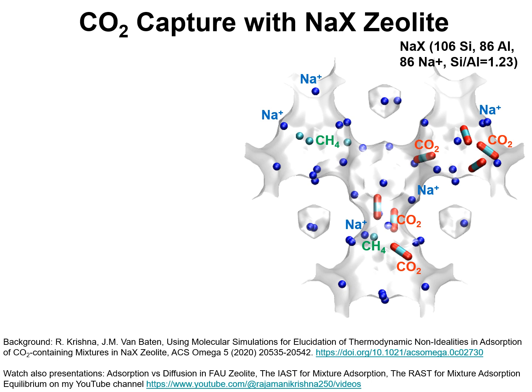PSA technologies. For post-combustion CO2 capture, 13X zeolite is considered to be the benchmark adsorbent with the ability to meet the US Department of Energy targets for CO2 purity and recovery. The commercially available 13X zeolite is a sodium cation exchange faujasite zeolite with silicon to aluminum ratio of about 1.2.